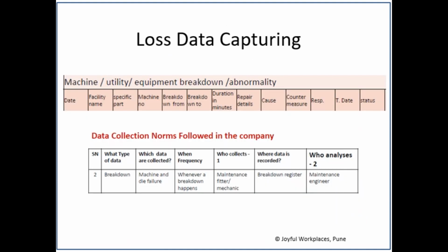This is the format wherein you should be capturing all the data related to breakdown. See what is happening on the shop floor. If you are only taking the data by calling it a breakdown, then that won't be helpful for us to do any kind of analysis afterwards. One needs to understand for what reason it was under breakdown, what kind of repair you have done, and what kind of countermeasure you are taking, so that it will give an input to preventive maintenance. So this is one of the formats wherein you can mention the breakdown abnormality.